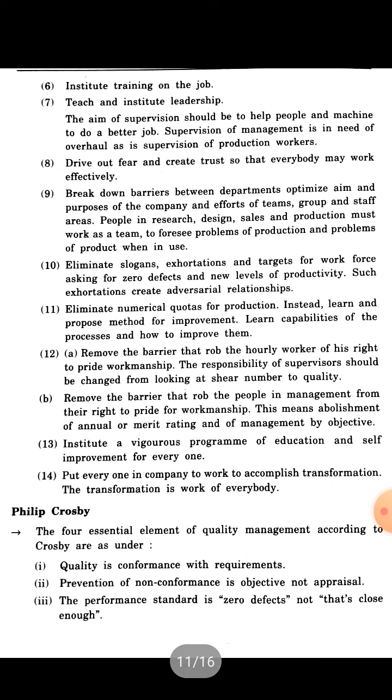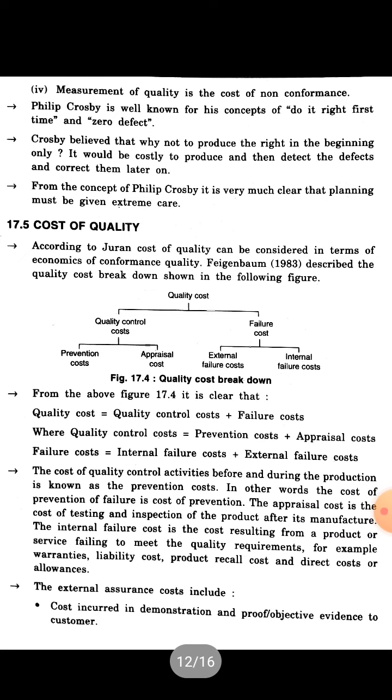Now next is Philip Crosby, the third expert. The essential elements of quality management according to Crosby are as follows. Quality is conformance to requirements, prevention of nonconformance is the objective, not appraisal, and third is the performance standard is zero defects, not close enough, and measurement of quality is the cost of nonconformance.